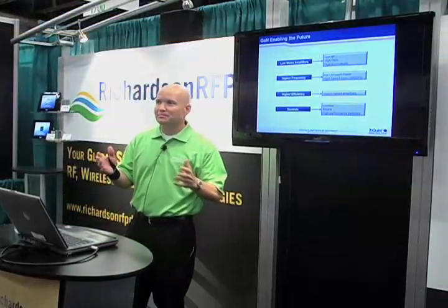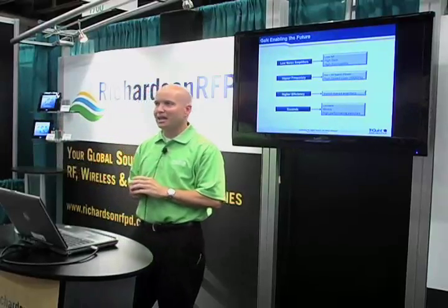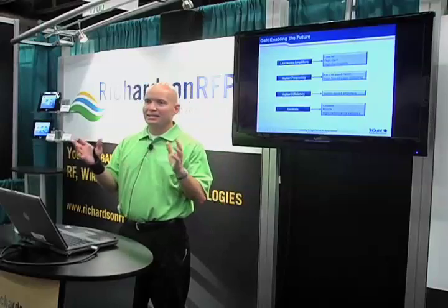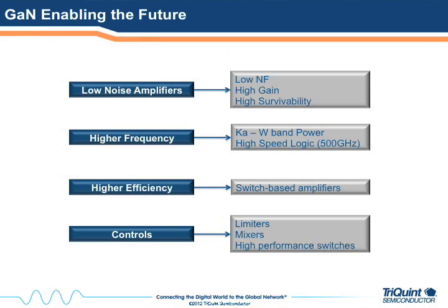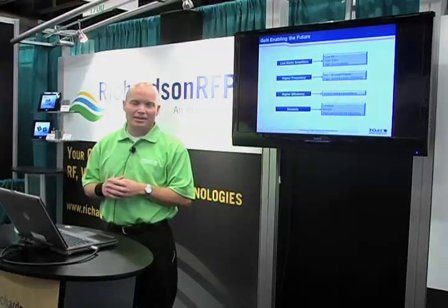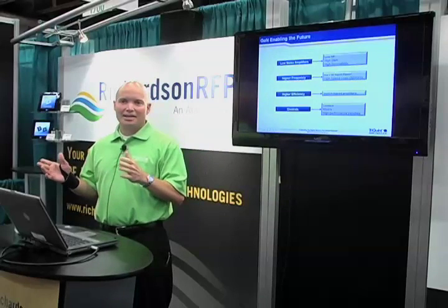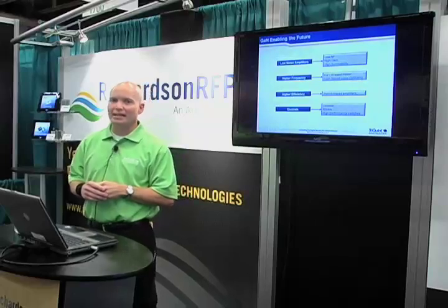So those are the products that are available today. What's going to be tomorrow and next year? What's GaN bringing to the table? Because as I said, a lot of the customers are saying, okay, we have the power amplifiers, what else can you do with it? Low noise amplifiers will probably be the next frontier for GaN product development. The main benefit it brings is survivability. We'll be doing some more research, some more testing throughout the next several months. But right now, GaN brings orders of magnitude improvement in survivability over gallium arsenide.